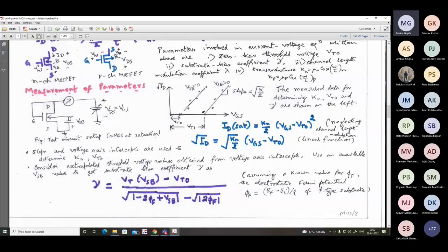It will forward bias. Theoretically it is not much of a problem, it will increase the threshold voltage, I think. Exactly. But normally it's not much of a problem. Experimentally, this is a single transistor. In actual circuitry, you cannot make this connection. Theoretically, you're right, there is no problem because the PN junction will remain reverse bias, because this is the N channel side, this is the P channel side. So P is always more negative with respect to source.